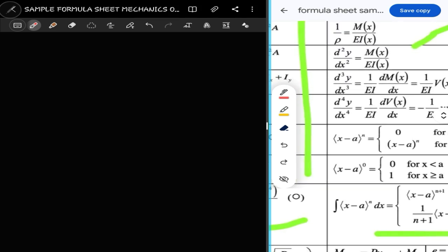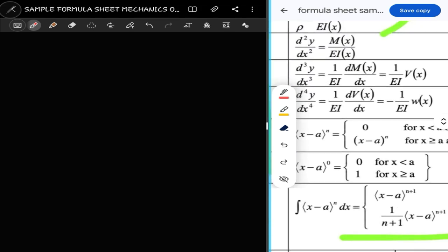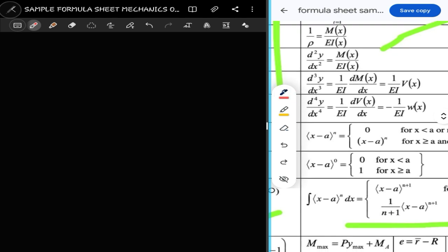Okay. One common thing that we are seeing here too is this. This is basically a discontinuity method where we use Macaulay functions to describe the concentrated load, concentrated moment, point load, or yeah, that's what we are using to describe them. So basically for that one, the basic form is this way. It's either a plus or minus depending on direction, and then you have the Macaulay bracket, right? And then we have an x minus the starting position of the load, right?